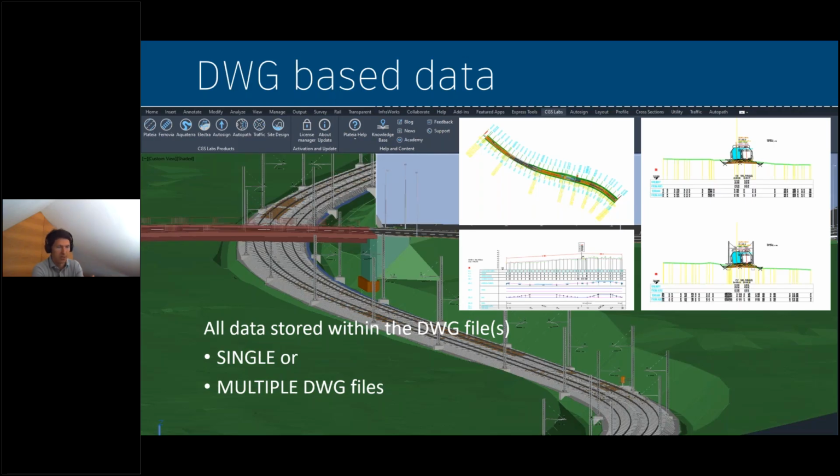There are properties also stored in the DWG, so you can export them to IFC, and the geometry to LandXML and other formats. Some used in Germany, also some others like REP, Oxtra. So all of those formats can be supported. Within Ferrovia, there's also a format supported by tamping machines from Plasser and Theurer, the geo and ver files, which can always be exported when you do the realignment tasks within Ferrovia.